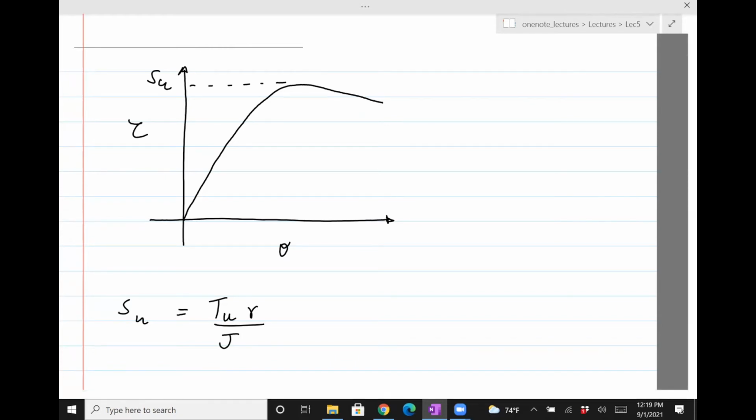So really, we see that we get the same behavior. However, you need to find the modulus of rigidity and get those slopes and so on. So you can't escape this. You have to do this test. Unlike compression, where you can assume that tension and compression have the same curve.